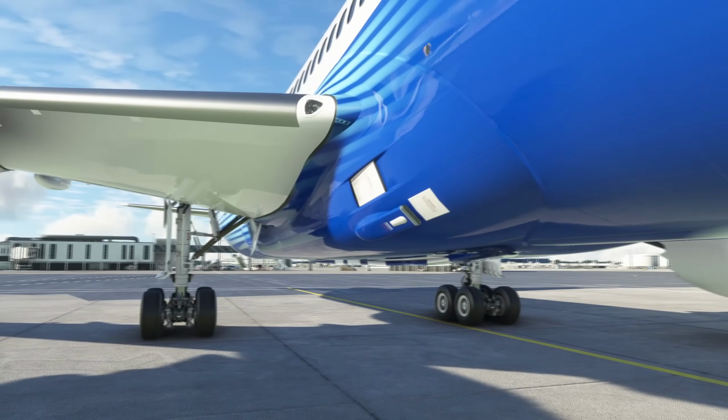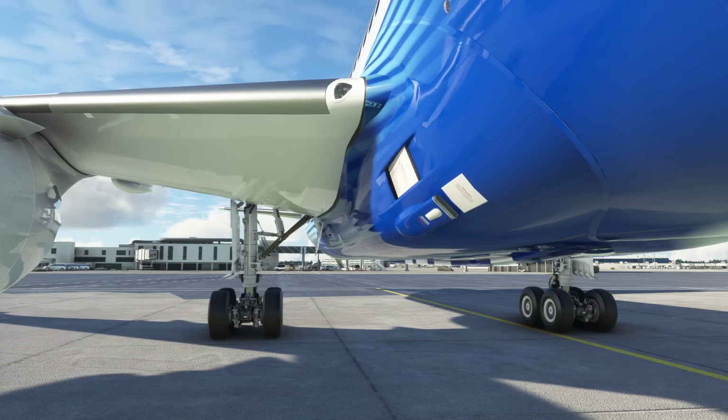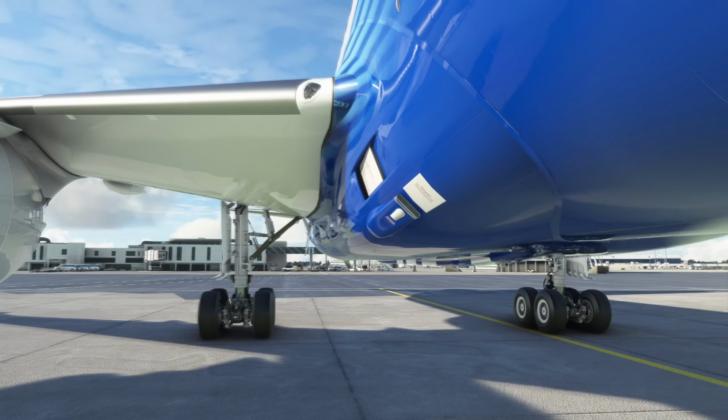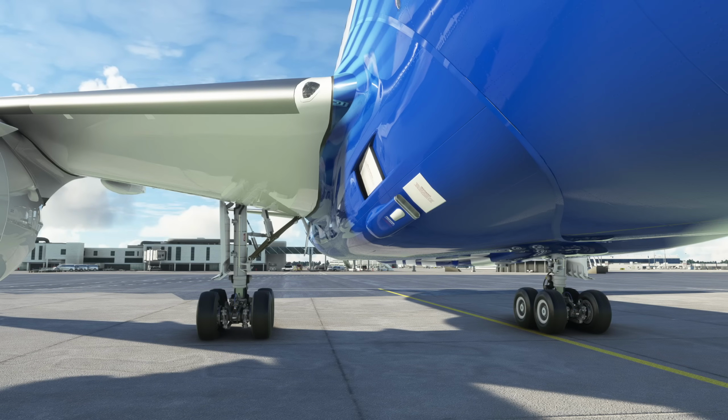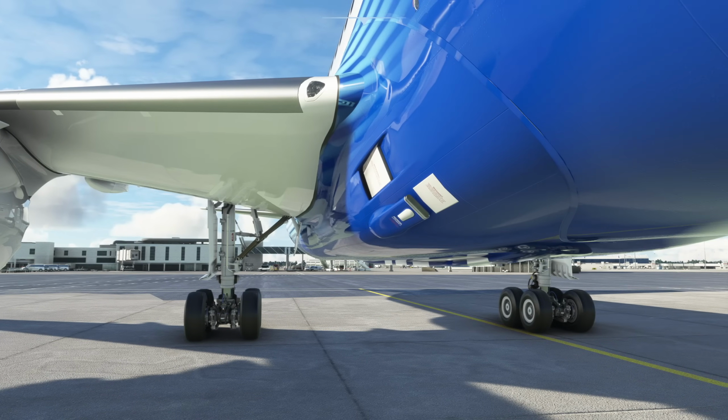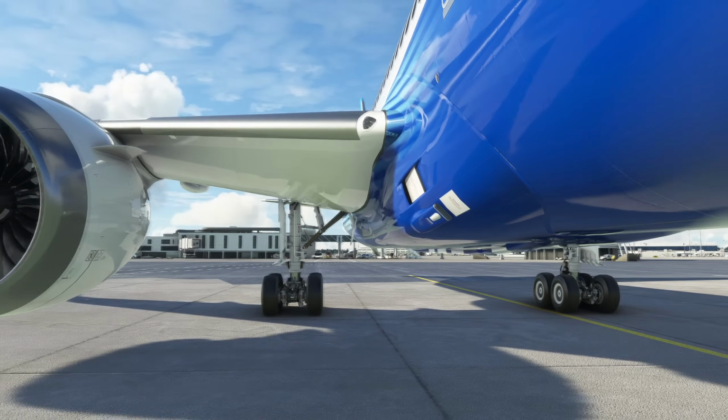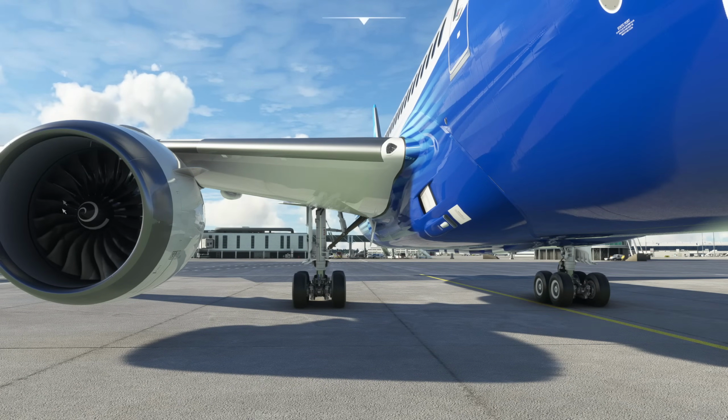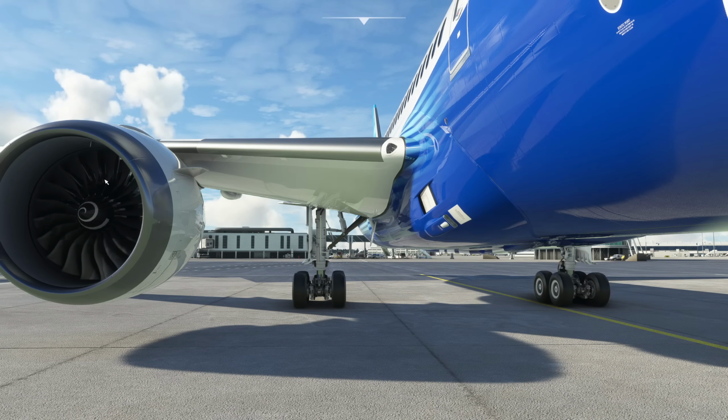The Boeing 787 does not use the traditional air system for pressurizing, and it's one of its best features, I would argue. Now, you'll probably hear me talk about this a lot as we go through the videos, but the 787's pressurization air does not come from the engines. On a normal aircraft, air is taken from the engine where it is compressed by the engine as part of its normal process of producing thrust. So the air is squeezed and squeezed, then it's ignited with fuel, and then that compresses it even more in a sense, and it flows out the back of the engine, spinning the turbines, which then spin the fans on the front, creating this cycle.